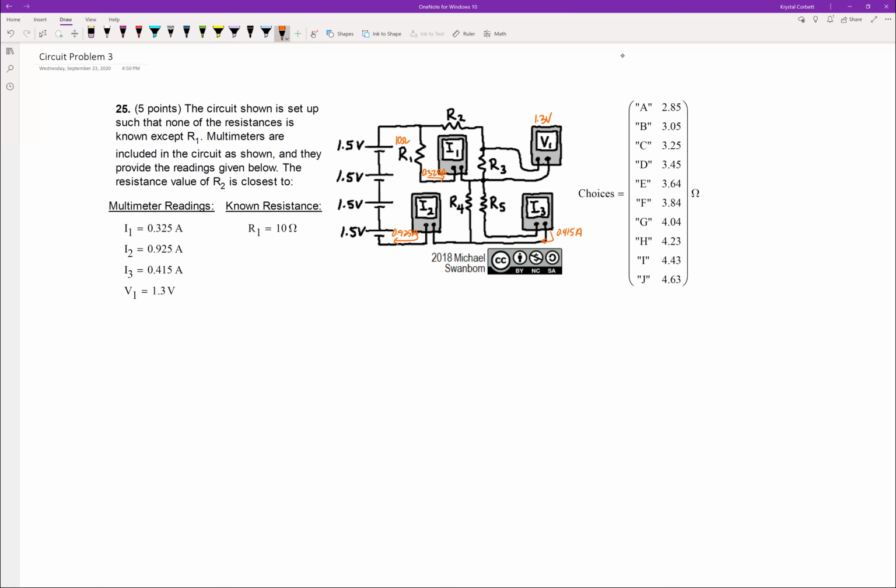When you have them in series like this, you can just add those together. 4 AA batteries, each 1.5 volts, together would be 6 volts. So I can erase the 4 sources and write them instead as one voltage source of 6 volts. Writing it as one voltage source helps to clean up the circuit. It makes it easier for me to see the connection of the resistors within the circuit.